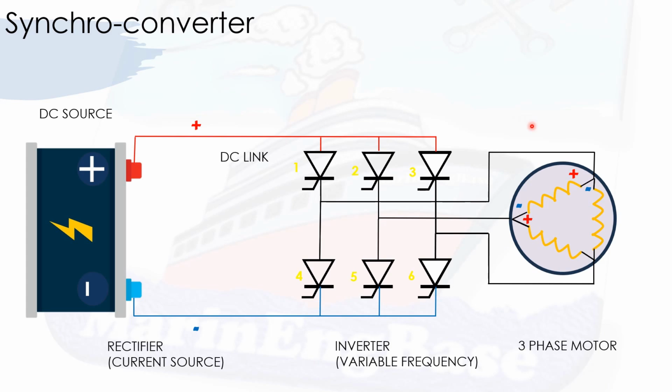To produce a three-phase supply, I have to use 6 SCRs, and we can see that we have connected all these 6 SCRs to the same DC source, and I can fire these SCRs in pairs so that the three-phase load, here a delta-connected three-phase motor, has each phase subjected to an alternating supply according to the pair of thyristors that we are firing.